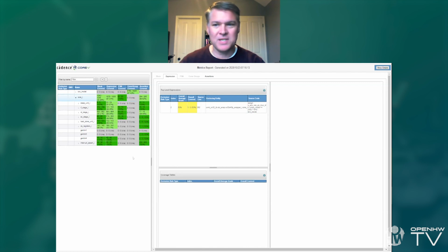With expression coverage, we're making sure that all of the internal logic, we're catching all those combinations of Boolean and sometimes logic values inside the RTL itself. FSM coverage, of course, making sure that the internal state machines of the core, all the arcs, all the states are properly covered in our tests. And then we do have functional coverage in terms of assertions, cover properties, and then ISA functional coverage that we'll look at. So for our block coverage, we're looking pretty good at this point.